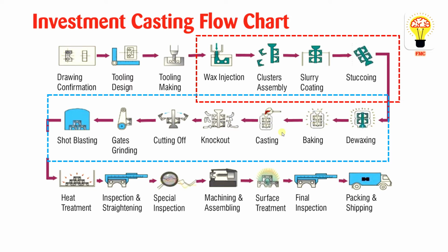So once the casting process is over, when the liquid metal is cooling down and it solidifies, we are going to crack the ceramic shell so that the fine ceramic particles are broken into a number of pieces. If you want, you can reuse the ceramic particles for other things. Then you are going to detach the parts. You can see we are adding some clusters, then we are going to detach them again. We are taking the parts, and we are going for grinding or finishing operation.